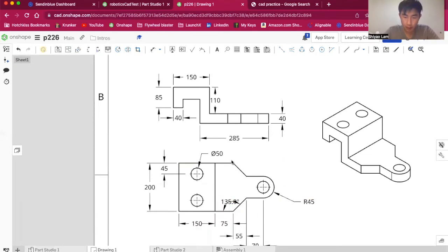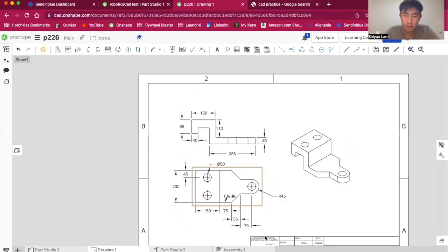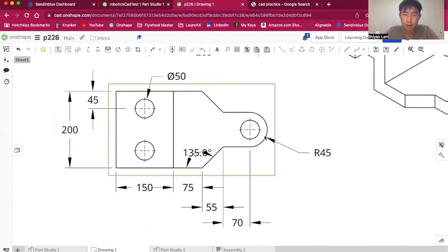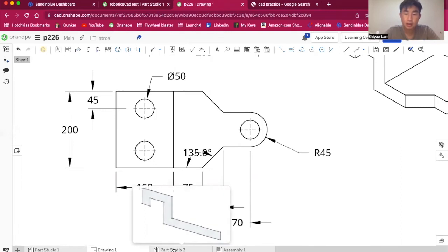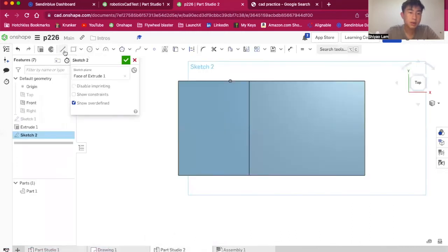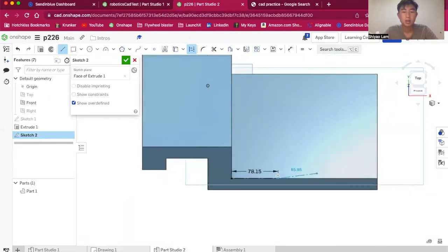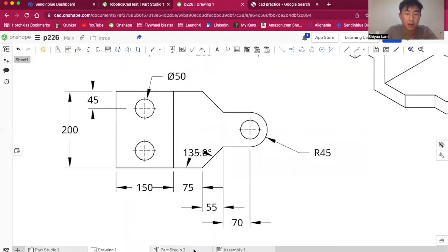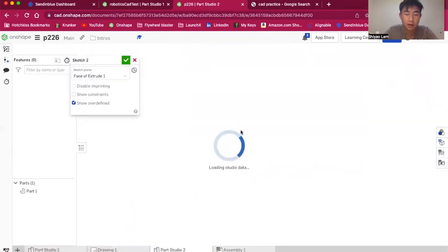And so let's CAD these. This is a slightly more complicated shape because it involves curves, but it's pretty simple. So this line is 75. It's very useful to use construction lines. So by pressing Q, you're going to activate construction, which means the lines are not solid, which means they're just sort of guides for you. They're not actually going to create shapes. So right over here, I'm going to sort of map out that shape using construction lines just to understand and lay down that shape. So 75 here.